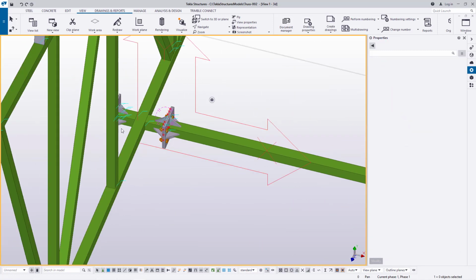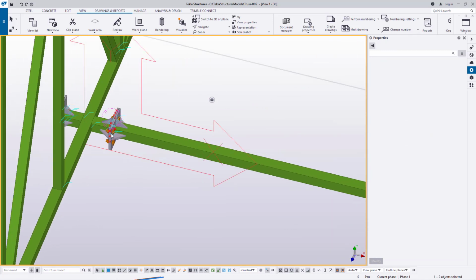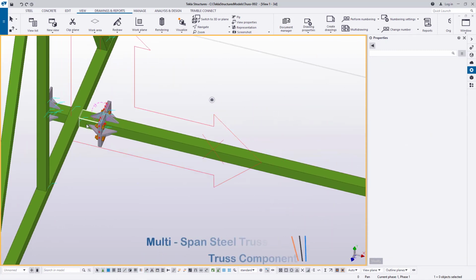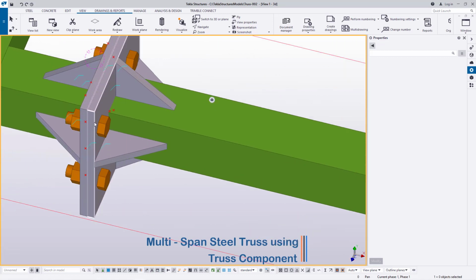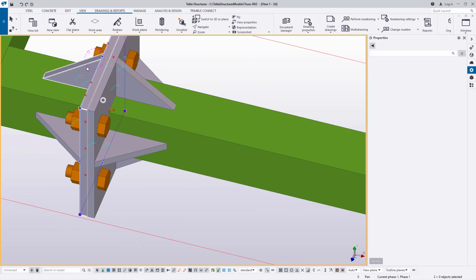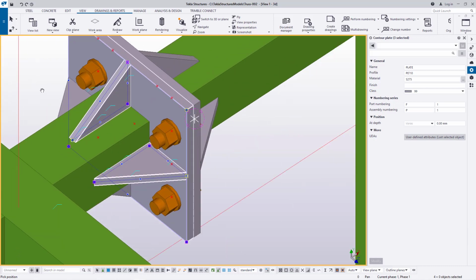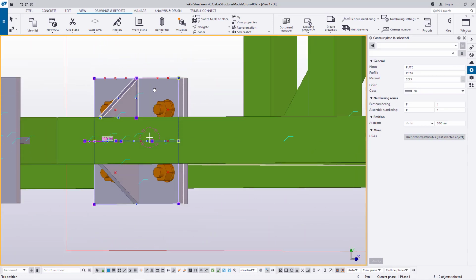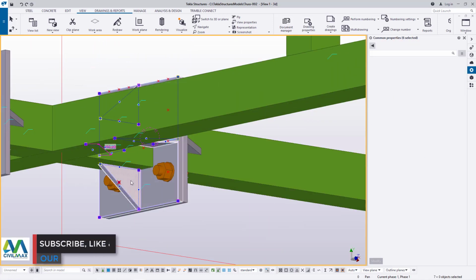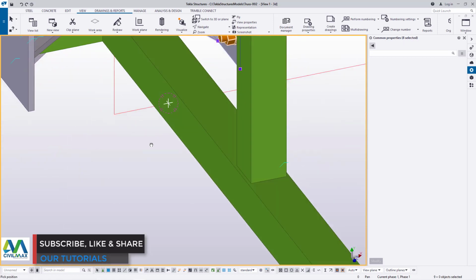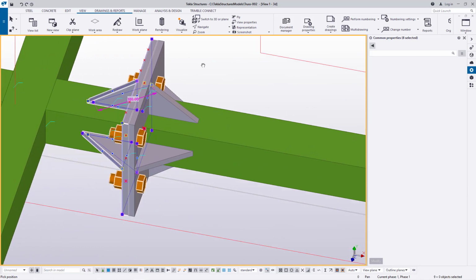So we want to transfer this component in the opposite direction. So how do we do it? We'll just select on this component, press Control, select on this component, right click, and select on the opposite. Right click and try to rotate this so that you'll be able to see the bottom end. Select, carry even the bolts with you, and select on that and try to rotate so that when you try to walk away, you'll be able to carry everything.